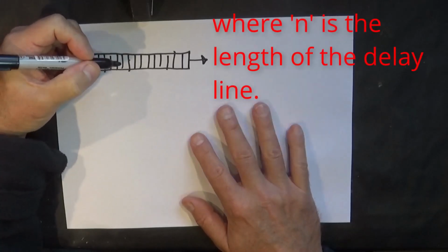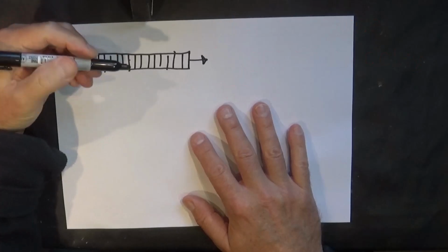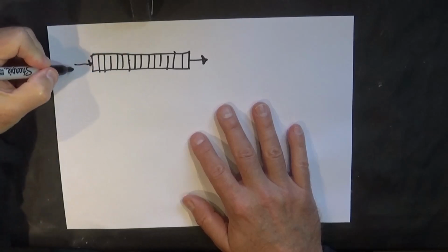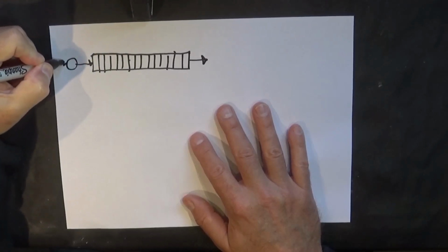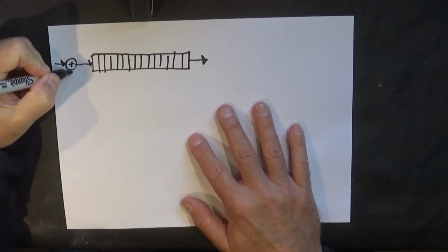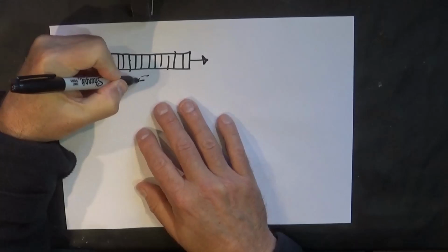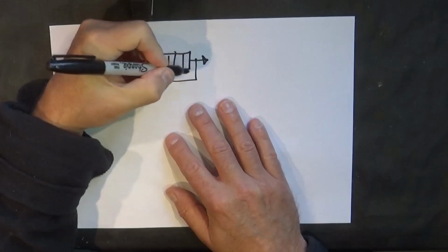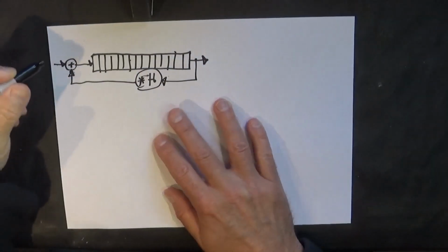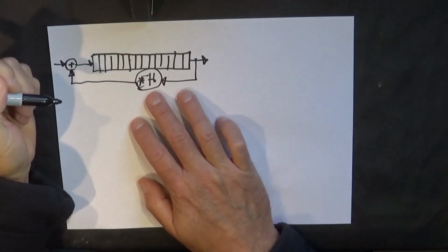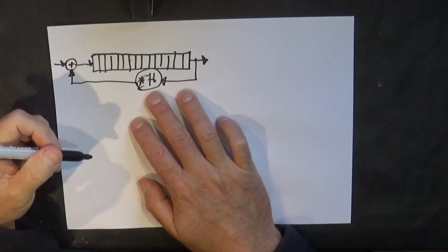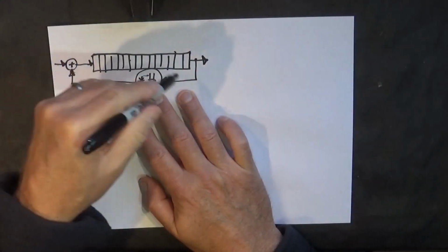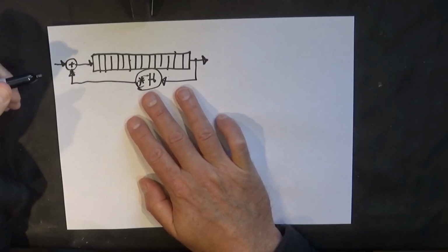Okay. And how do we make that into a resonator? It has lots of uses, but we want to make it into a resonator. Well, we have our signal going in here and add some feedback. Sorry, the drawing's a bit scabby. The feedback gain is less than 1, because obviously if it was bigger than 1 it would just explode and overload.